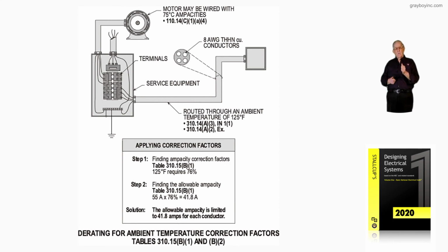What size is the overcurrent device above 18 amps? 20. What's the size overcurrent device above 19 amps? 20. So the solution and the answer, 240.4D and Table 310.16, requires a 20 amp device and number 12 20 amp conductors, and this calculation, applying the golden rule of items 1 through 4, has been met, and this installation complies.